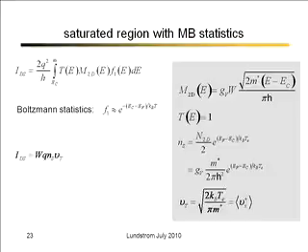And I can go ahead and work out that integral, and I can recognize some quantities, and then I can rewrite it as width times charge times the density of electrons in the channel per square centimeter times this thermal velocity, which again is just the average velocity of electrons in the transport direction under thermal equilibrium conditions. I guess the final thing I need to do then is to put in what I know about MOS electrostatics.